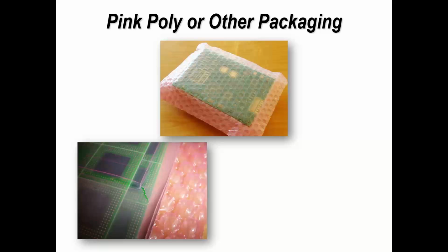Okay, so packaging. Now, the majority of boards we get today, we use today, comes in some form of shrink wrap packaging. And it comes down to what you specify. If you don't specify anything different, this is the type of packaging you get. I'm not saying this is bad, I'm just saying this is the type of packaging you get. And normally speaking, you get shrink wrap over 20, 30 boards, whatever you've specified. And the key thing is to make sure that the boards are protected, the edges are protected, as well as the actual product during transport.